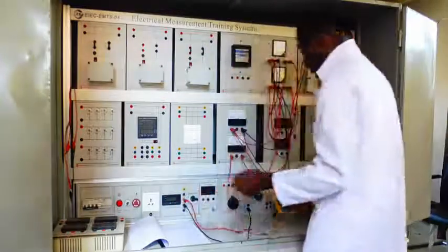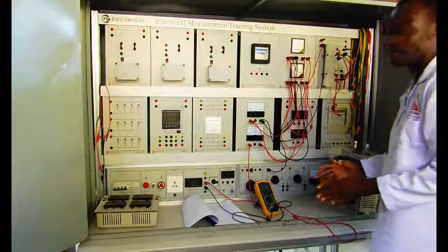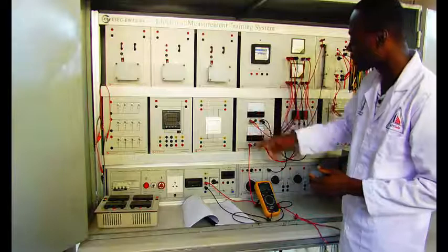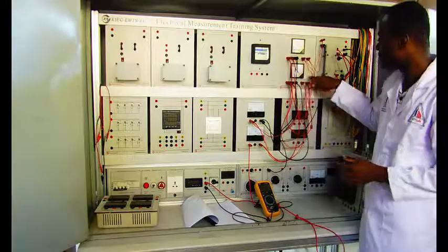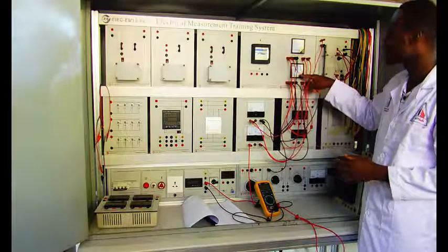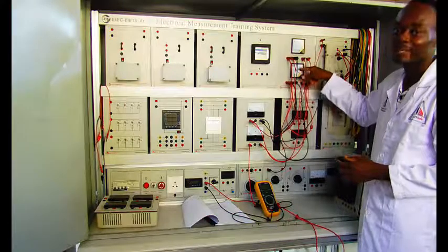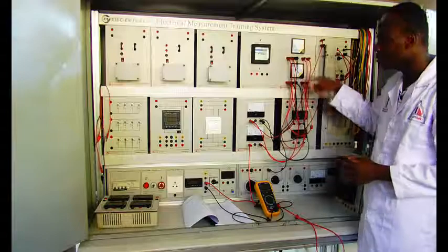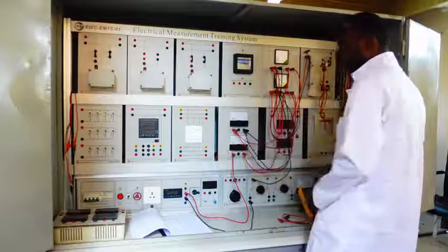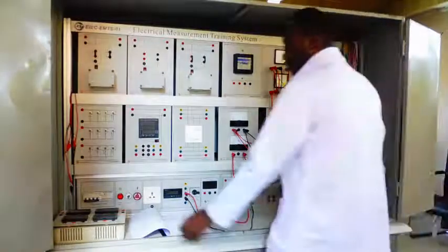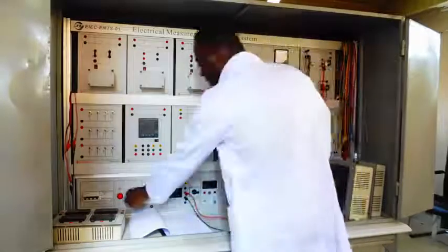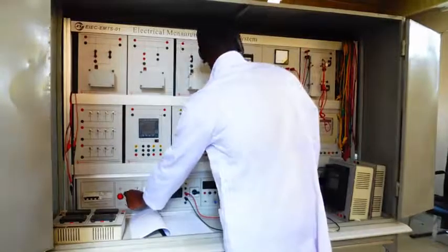So I'm done. Since we have not energized it, our meters are at 0. But when we look at the power factor meter, it is at 1. Also we start from 1, which is 100%, downwards. Okay. I'm going to energize it. So I'm going to bring the system on. Turn the circuit breaker on, then the key.